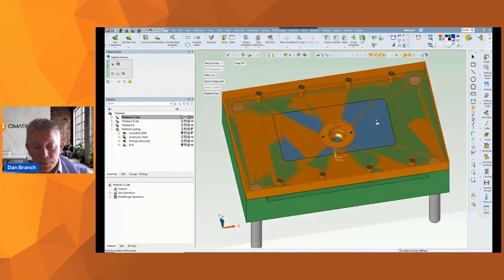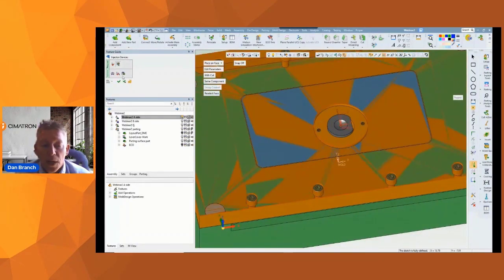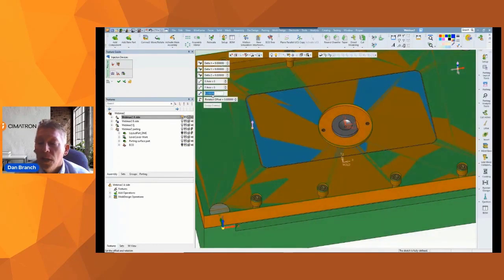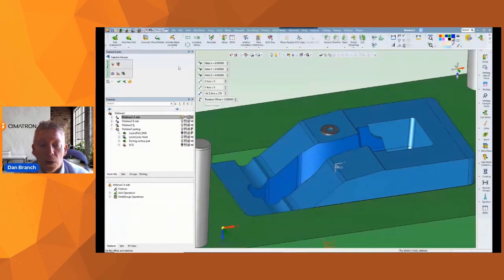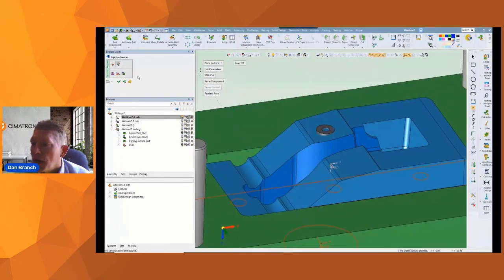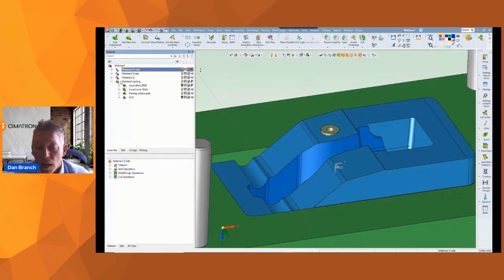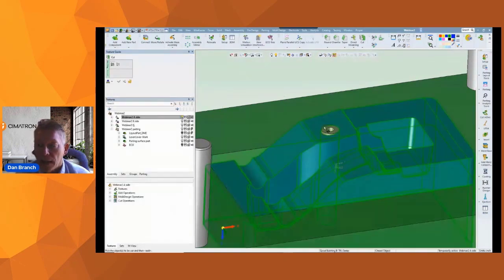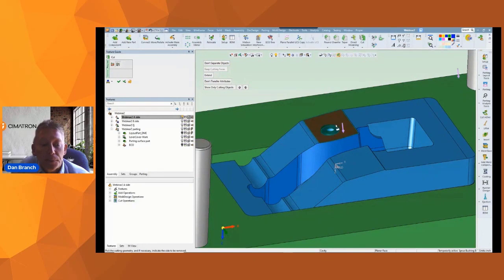Cimatron, of course, really excels at simplifying the placement options for mold components. I already have a reference point on the mold base, so I can drop it in, and then it's easy to rotate the bushing around. In this case, I want those water pipes to be shorter. And then I also want to choose an option here to cut with this part. Doing a cut means that I want the part being added to make its own correct pocket. So in this case, it creates the hole in the cavity for me.